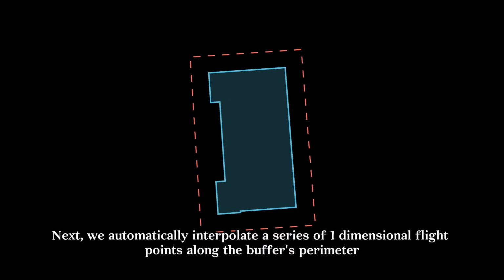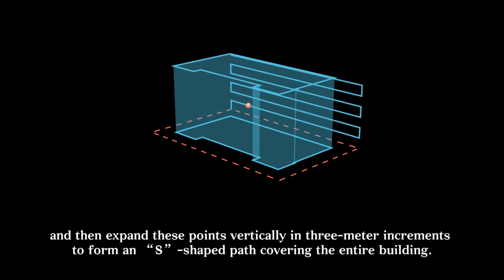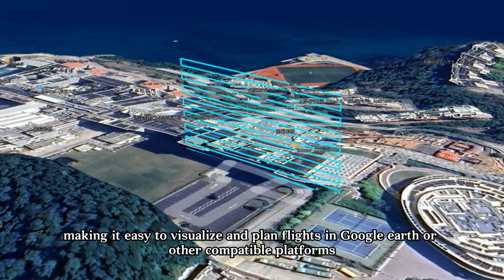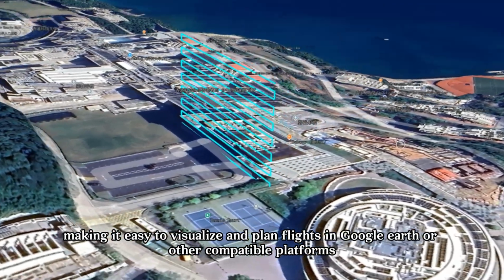Next, we automatically interpolate a series of one-dimensional flight points along the buffer's perimeter, and then expand these points vertically in 3-meter increments to form an S-shaped path covering the entire building. Finally, we export these automatically generated flight points to a KML file, making it easy to visualize and plan flights in Google Earth or other compatible platforms.